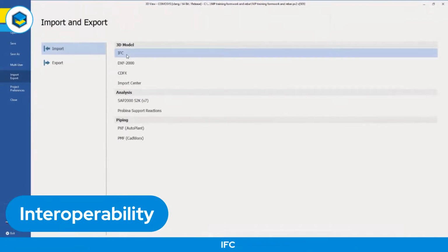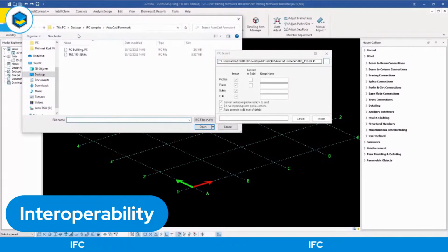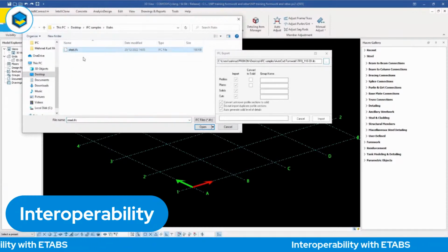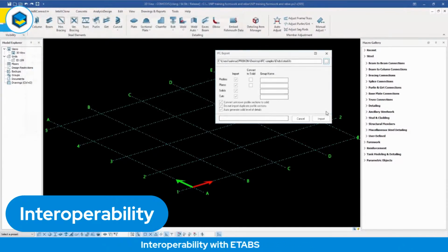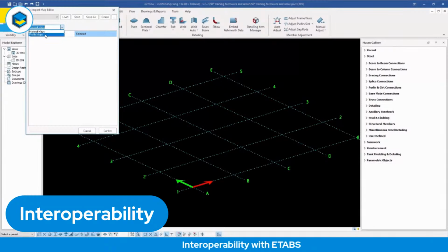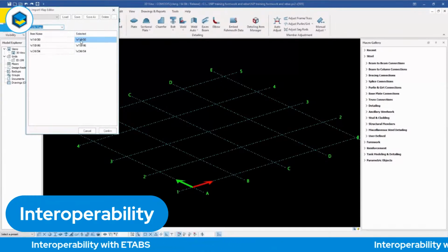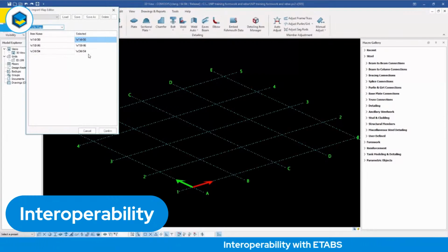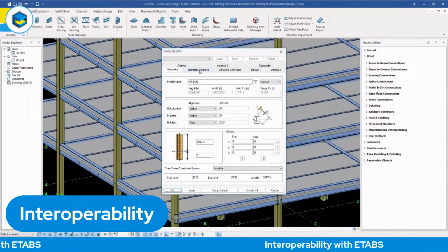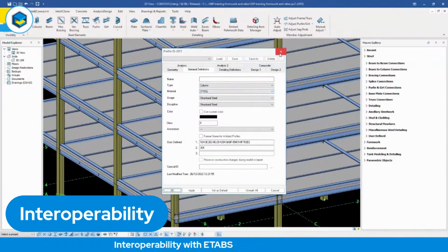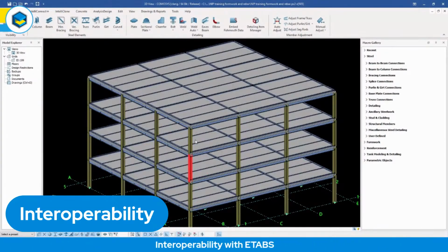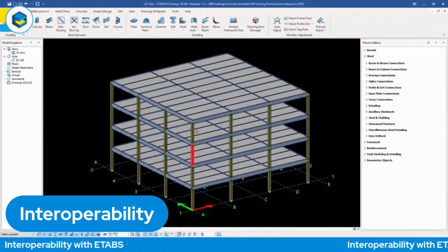This time around, let's choose another IFC file, and let's choose it from a different program. So let's do an ETABS example, for example. This file has been exported from the ETABS program, and let's open it. And once again, press the import button. This time it hasn't found any material definition inside the file, so that's interesting. If I go to the profile maps, it has found these three profiles, and it has also found the corresponding COMOSYS names in the profile database. So we can just confirm that, and immediately the file has been imported as native objects, but their material definition has been set as default because it couldn't really find any material for them. So this is once again a very easy and quick way. And like I said, in this case, you can just continue your modeling directly in COMOSYS because you now have the model in the native format of COMOSYS.